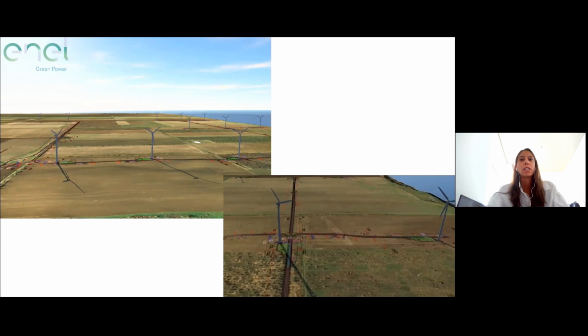Our goal is to check parameters such as the radius of each alignment and the vertical profile slope, as mentioned before, for which we have specific requirements in our technical standards. These present an alternative to the design criteria that can perform geometric design checks only for limited design parameters. We know that we are at the beginning of this process and we are checking only a few parameters, but we understand that Dynamo gives us big flexibility and we can evaluate more parameters in the future.